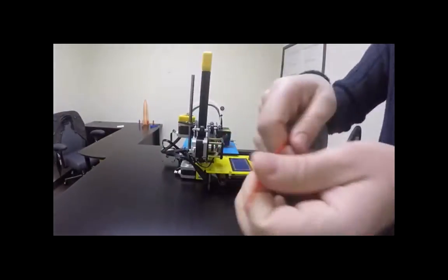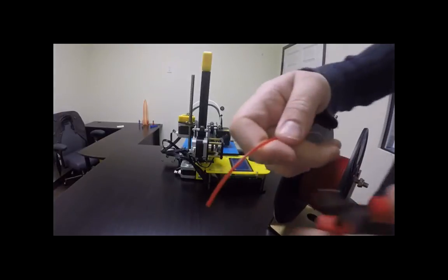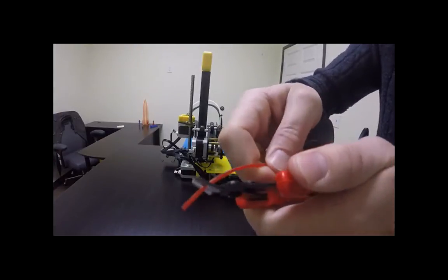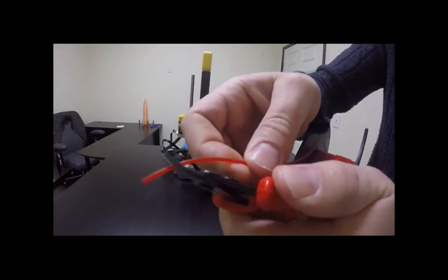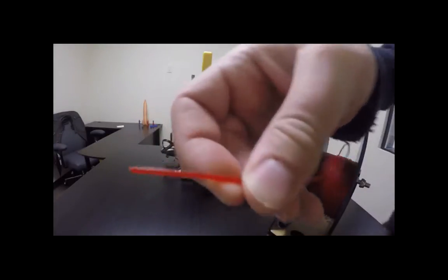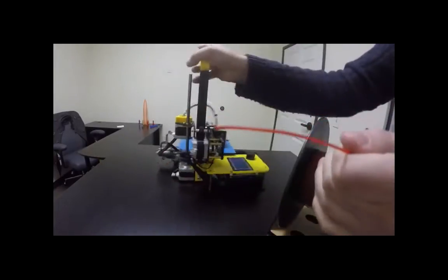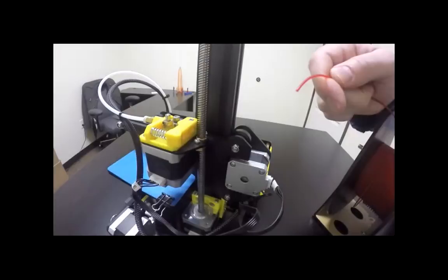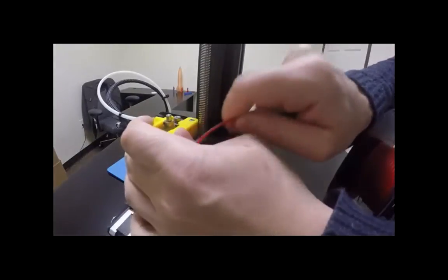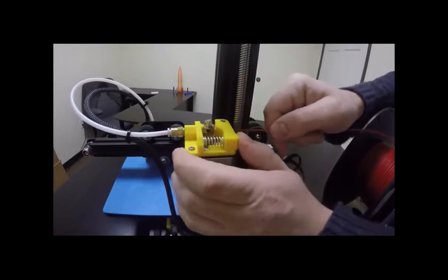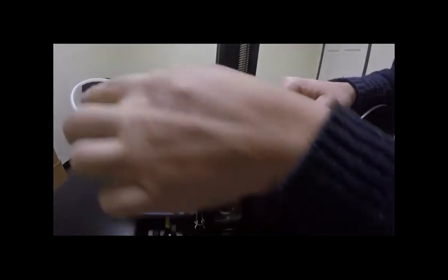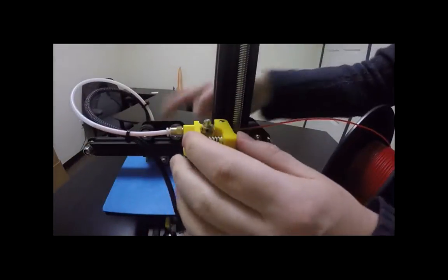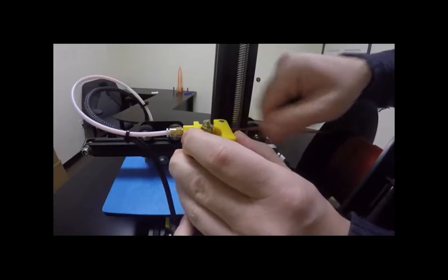Before you put the filament in, you'll want to clip the little plastic zip tie off of the filament, and then clip the end of it like this, so there'll be kind of a point. That's what you want to fit into the printer itself. Right here, you can see there's a little hole. When you squeeze this, it'll go through this hole, and when you squeeze it, it will keep going through, all the way through to the very end, all the way down to there. So you keep pushing it through.